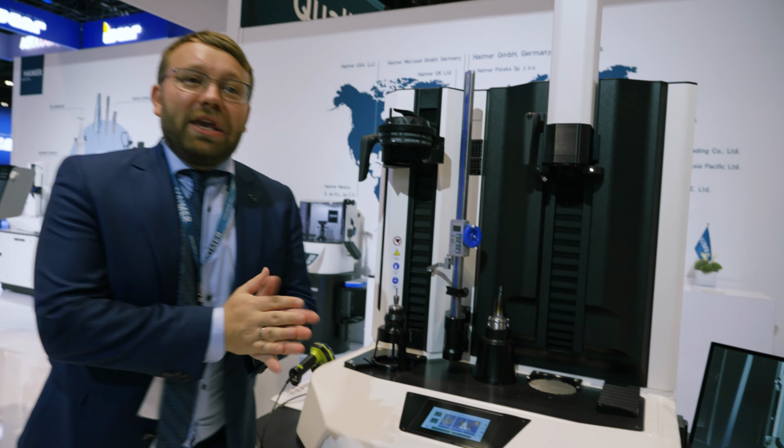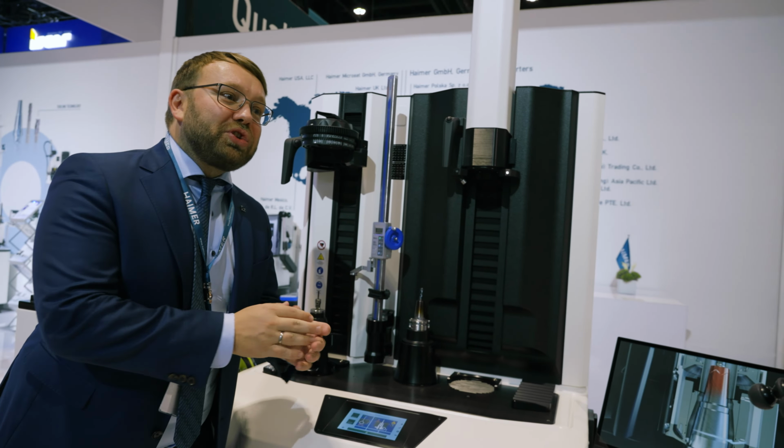One more thing I want to show you is also a new shrink machine. Here we see our new shrink machine with our cyclone cooling. You see it in this animation. It's an air water mist that's much quicker in order to shrink the holder and cool the holder. Here the coil is also adjusting fully automatically, like we've seen before in the video. We take out the cutting tool, put it in.